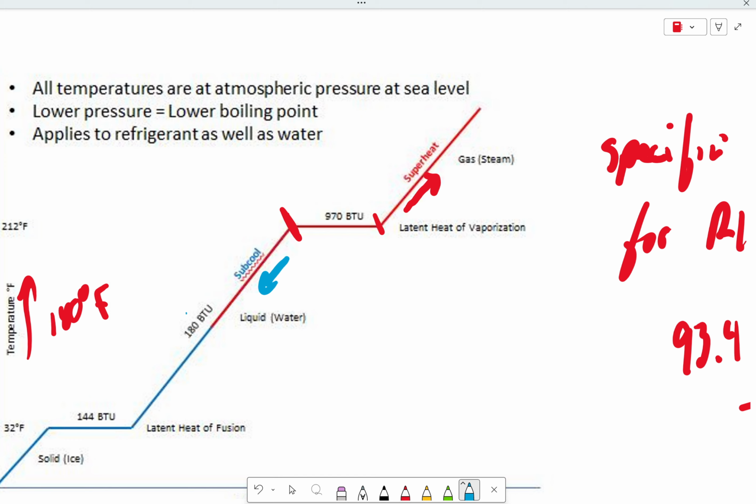And then if I start cooling down the liquid, again, it's kind of pointless. It's a waste to spend a whole bunch of time cooling down the liquid, because we're back to that, in theory, 1 BTU per degree Fahrenheit that we cool it down. When it comes to superheat, you don't really want to have a huge amount of it happening, okay? Because it's not a very efficient way of transferring heat. When it comes to subcooling, this happens in the condenser. Again, it doesn't really matter how much happens as long as some did happen, indicating that the phase change happened. Does that make sense? Okay.